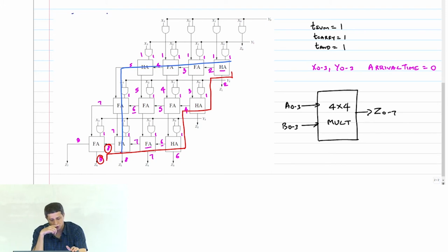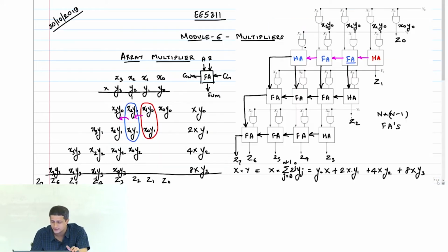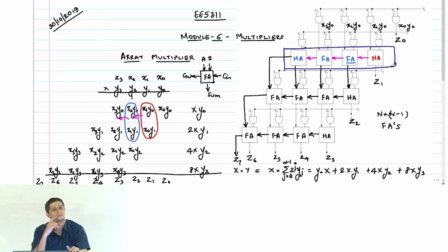So you also notice what is happening is, if you take every single stage here, right, if you take a single stage, I run out of colors, okay, if you take this guy, it's basically like a ripple adder, right? I'm basically just rippling my carry through that stage. Each row I'm rippling my carry through that stage, correct? So that is really not helping me.